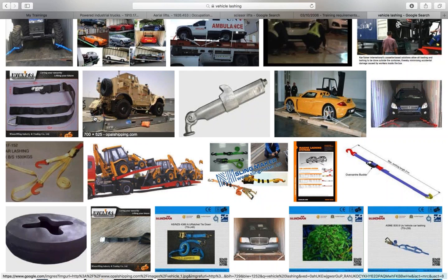Okay? So in addition to personal safety, also be alert, right? Don't jump on and off of moving equipment. Make sure that it's stationary, parked, and braked before we get on it. Equipment has to be at a full stop, right? Park and brake engaged. Also, prior to entering or exiting the equipment, maintain 3 points of contact when getting on or off of the equipment, and know the location of any first aid equipment, fire extinguishers, and emergency telephone numbers. Make sure any equipment that we have has that fire extinguisher on it, and that any safety devices and safety guards it comes with are all in adequate shape as well.